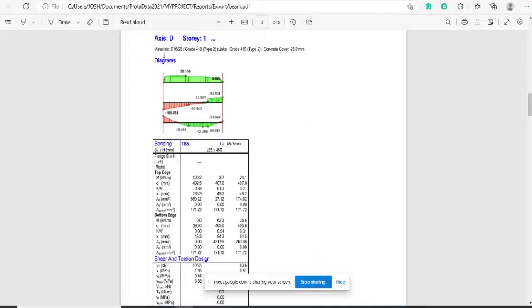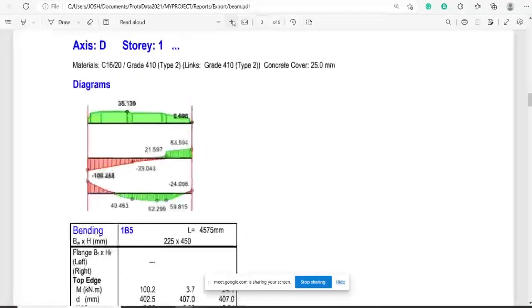That's it. This is simply supported. Now let's just make a very simple example of what I'm saying. According to our manual design, our first principle formula, if you want to obtain the maximum moment of a simply supported beam, we know we use WL square over 8. But if you use WL square over 8 here, your value will be a little bit lesser than or greater than what you have here.